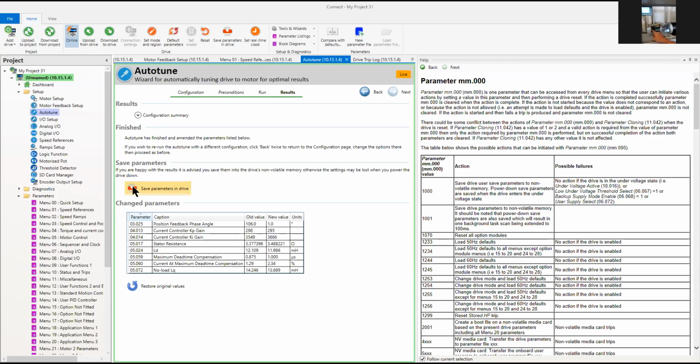So now this motor can go up to 3000 RPM. This motor drives the induction motor. The induction motor now is practically the load for this motor. We auto-tuned this motor for two PIDs, stationary and rotating. You have the parameters for PID now.